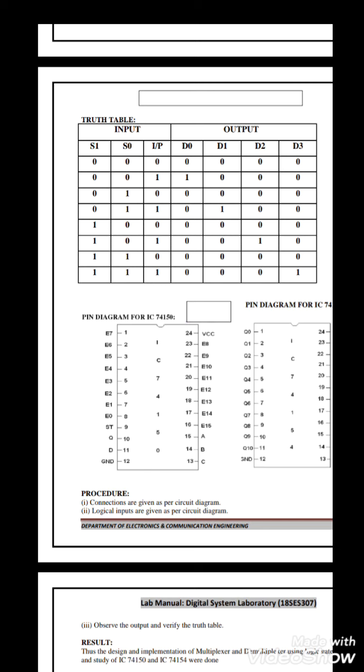So already you know the basic concept of the multiplexer. We give 16 input lines, and from those 16 input lines we get only a single output. How do we get only a single output from 16 inputs? How many selection lines are used to do that operation? 16 inputs are available, and from them we direct only one output, so you require 4 selection lines.